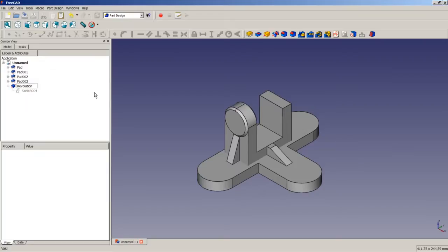I also experienced sometimes a little bit of trouble when sketches are mapped to a face. If you try to copy them, sometimes the sketches will have some linkages to some geometry or whatever. What really works well is if a basic sketch which you copy to the clipboard is linked to one of the basic planes and not to a face.